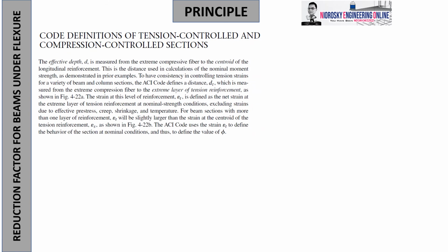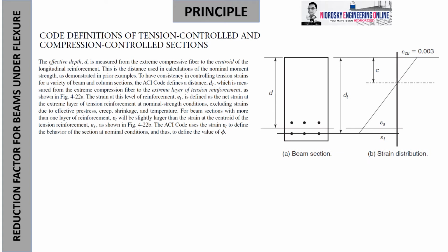So in figure, ito po yung magiging itsura niya. So, kung naalala po ninyo, yung effective depth D is the rebar center, as explained already in one of my past video lecture. But the D sub T is taken as the last layer reinforcement, okay, up to the nearest, up to the compression fiber of concrete extreme, no? Extreme compression fiber of concrete, okay? So, yung sinasabi ko kanina, ito yung layer of reinforcement na pinakamalapit naman sa tension fiber of concrete, okay? Extreme, sabihin na natin extreme tension fiber of concrete.